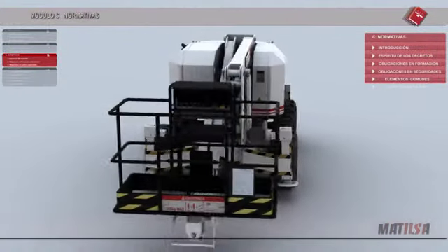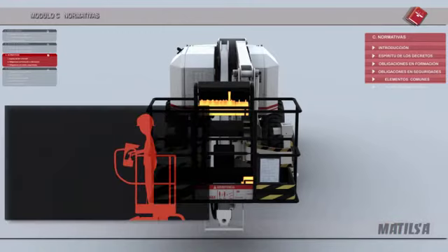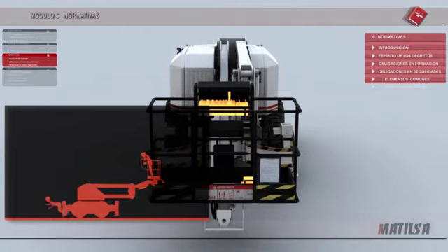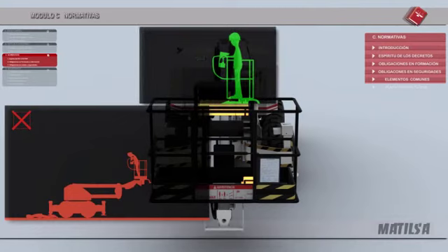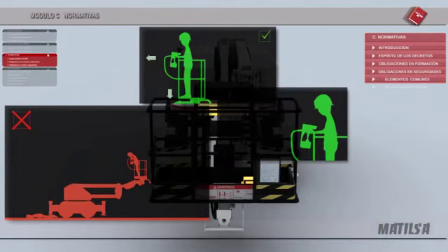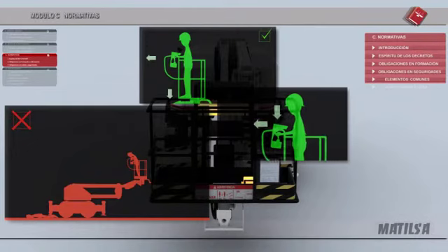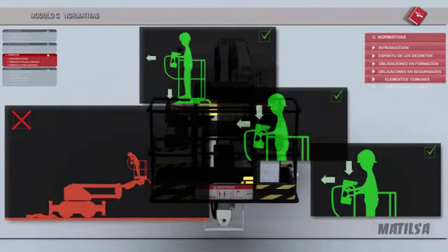Compulsory buttons. The machine will have to be equipped with some devices that prevent the platform from being set in motion by accident. This is intended to prevent the worker who is in the basket operating the controls involuntarily by fainting or through any other unintended action, thereby setting the machine in motion and possibly causing an accident. Each manufacturer may choose whether to set a worker on board pedal or a button placed on the transport controls or on the higher steering board. That is to say, it will be necessary, apart from moving the control, to press this button in order to set the machine in motion.